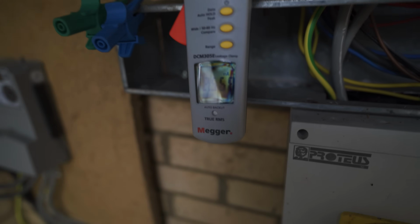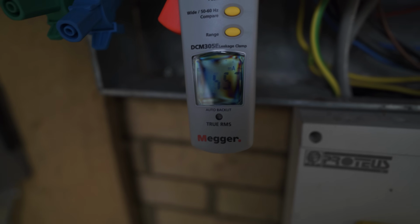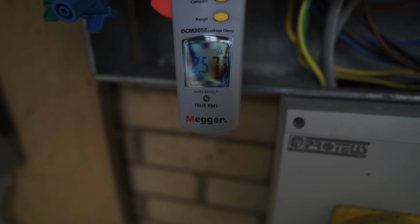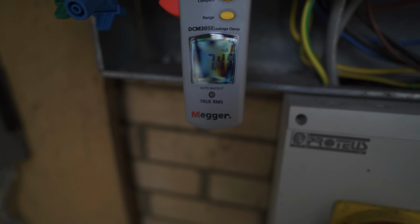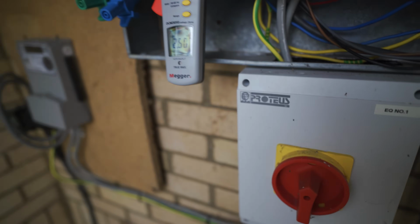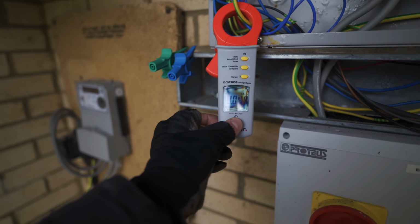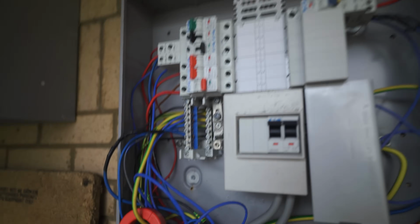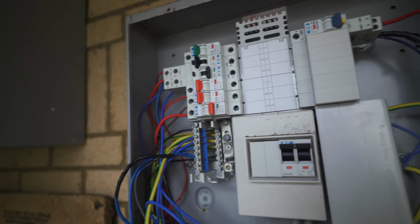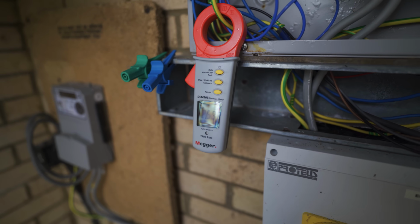But what you'll notice on startup, when I first turn it on, it jumps up to 27 that time, 21, 23. A lot of the time it's higher, 26. So on startup, there's between 25 and 30 milliamps of earth leakage, which is obviously going to pop that RCBO before it even gets started. So that's what the problem is, and that will be due to that live and neutral earth fault.